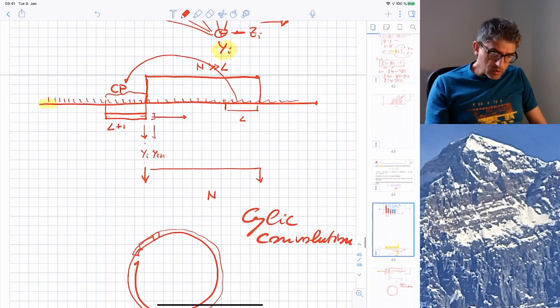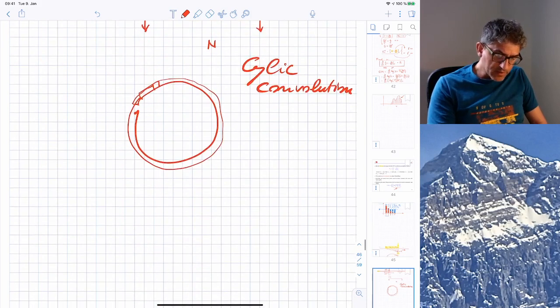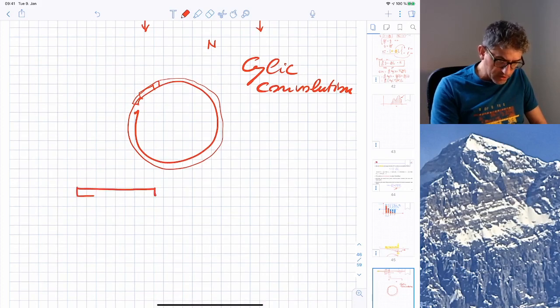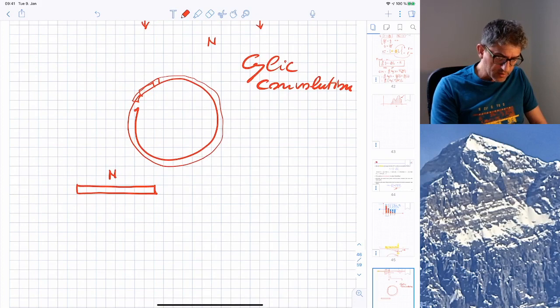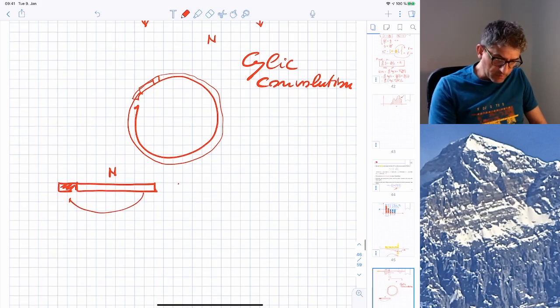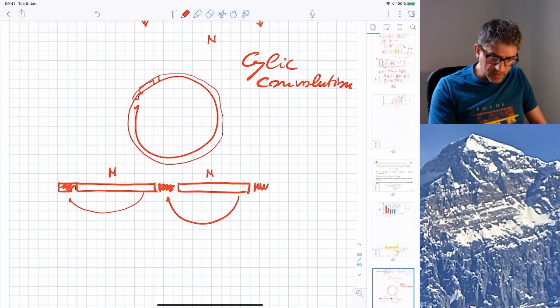And now what we can do is stack all these blocks, each one with this cyclic prefix, one after the other. So instead of sending simply X, we are going to send the following thing. We have a block of n fresh symbols and its cyclic prefix. This is just this part copied here. Then we have another block of fresh symbols here, and its cyclic prefix. Okay? And we keep going like this: cyclic prefix, block of n symbols.